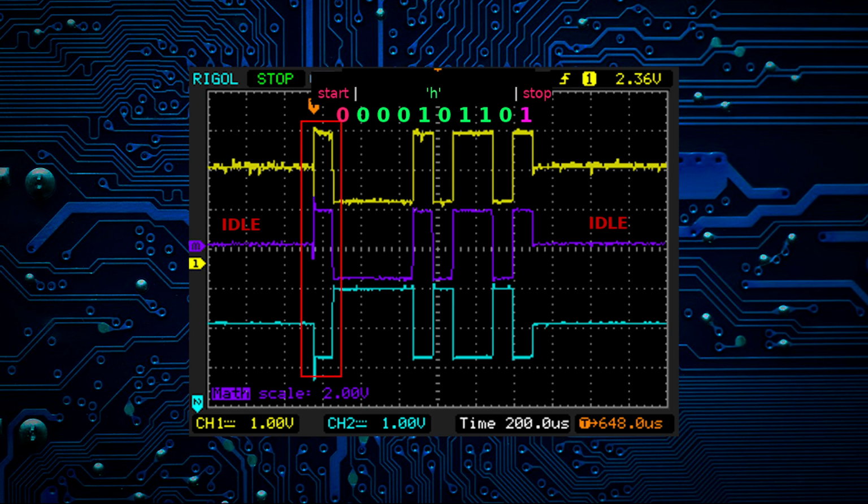This is an example done with the UART protocol, but how will it work with other protocols? In the RS485 interface, we have to use differential pairs for both communication and clock channels. In the case of UART, we do not have a clock signal, but in protocols like SPI and I2C, we do have a clock signal. But for example, in SPI, with the chip select pins, it may or may not be necessary to use differential pairs, depending on the case.